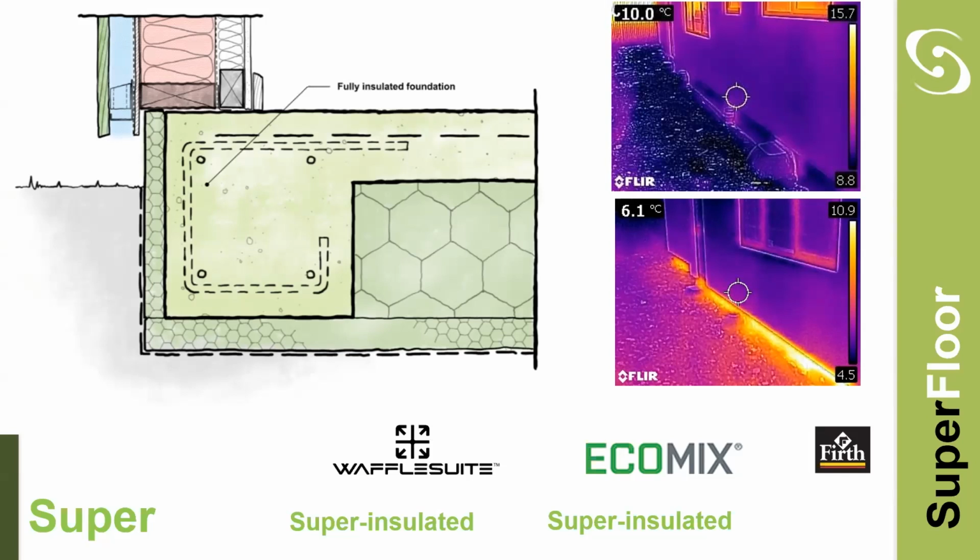Moving on from that, things like toxic materials: the International Living Future Institute have a red list, and they have a list of building materials that have either ingredients or chemicals in them that potentially can be harmful to living creatures or the environment. So we use that in the back of our mind as to what dictates the materials that we're going to use in these jobs. So things like trading off different products like plywood or any timber that's treated with CCA, which is copper, chrome, arsenic, and swapping that out to things like micronized copper azole, which is good. People use it in playgrounds and in veggie gardens, whereas putting chromium and arsenic into the soils is not great.